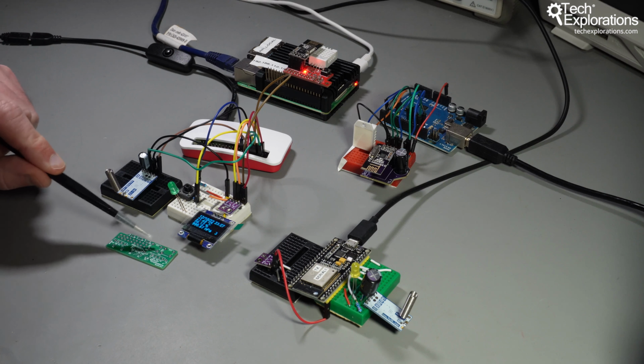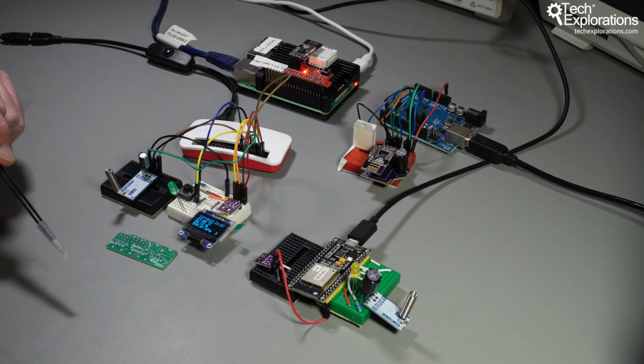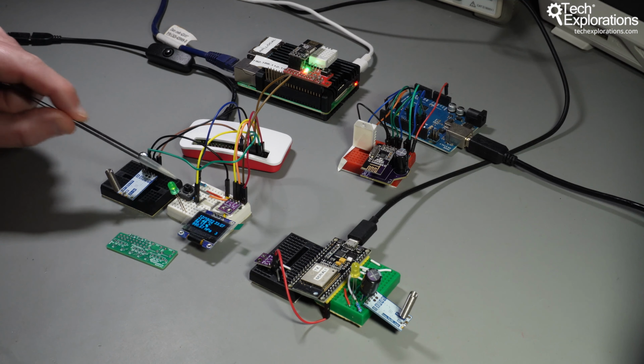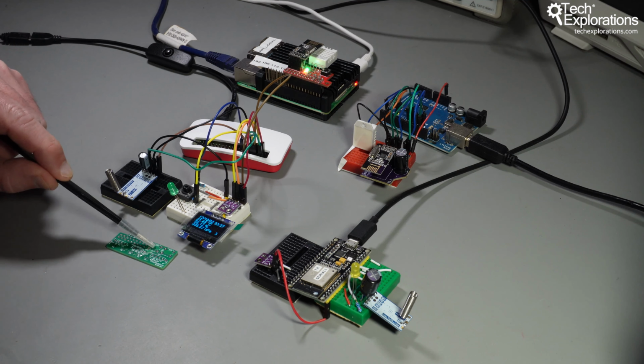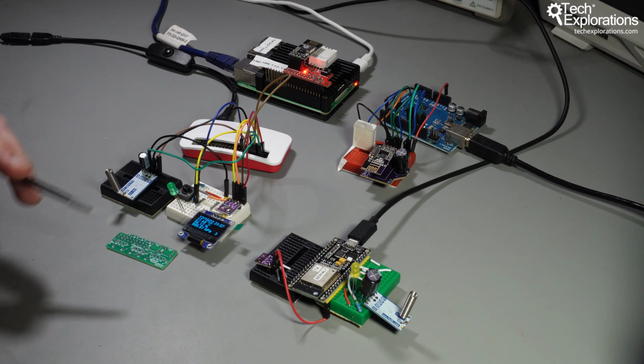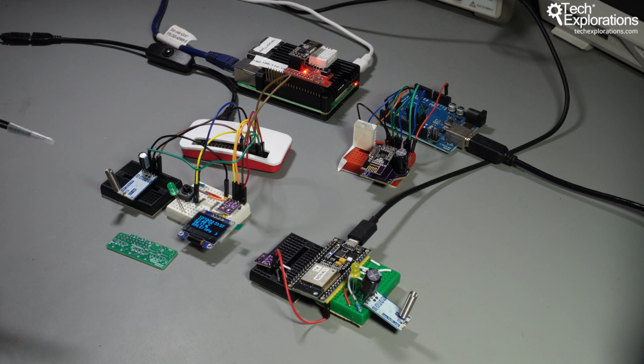So for example, you can have an additional button here that could trigger an email. This is number 1 button. You can have another button here, number 2. You press that button and then the Raspberry Pi will send you an email that summarizes things such as current environment conditions on remote and local device, time and date, where the report was generated, and how much space is available.